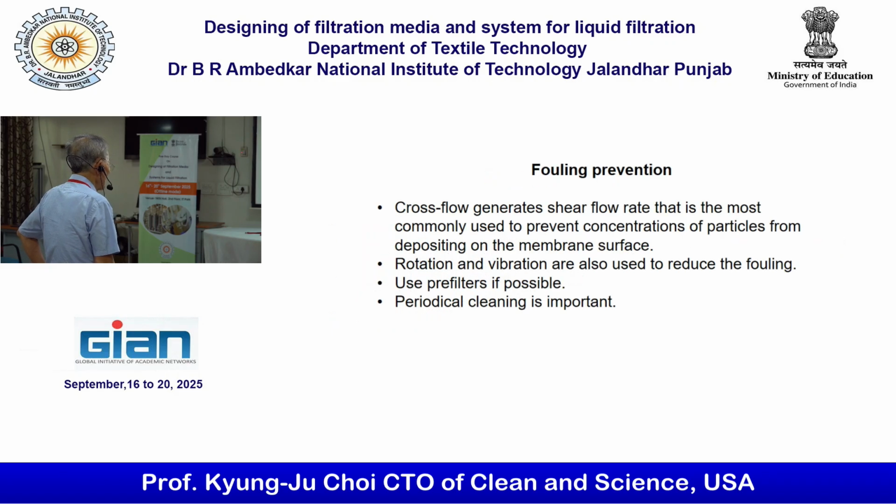Fouling is a big issue actually. That's why they use cross flow, generally shear flow. Rotation and vibration are also used to reduce fouling. Certainly, a pre-filter is really important. Periodic cleaning is important as well.